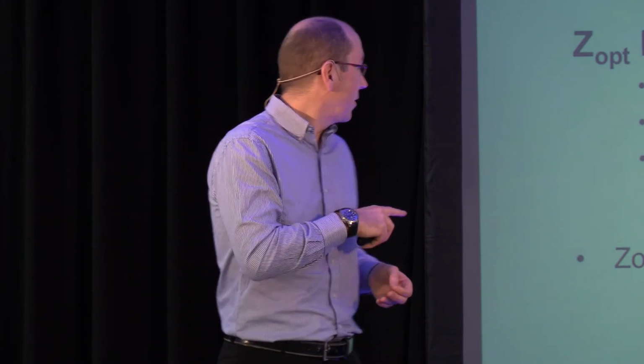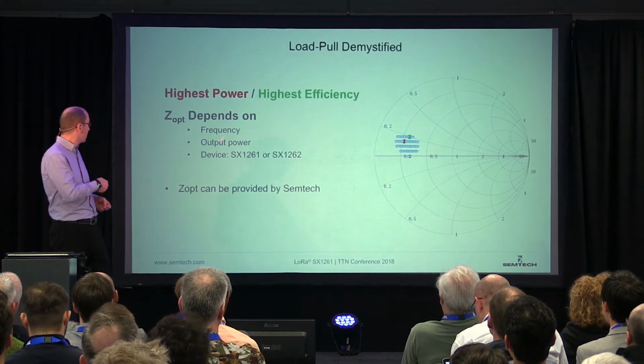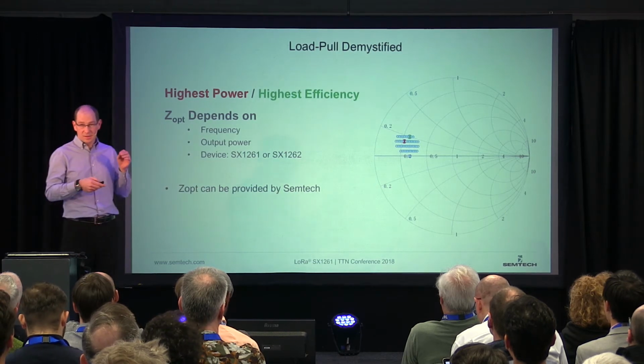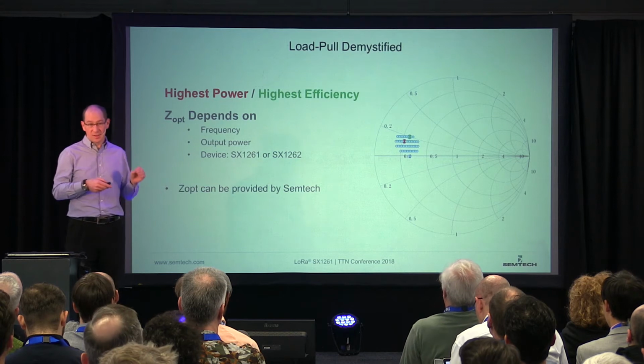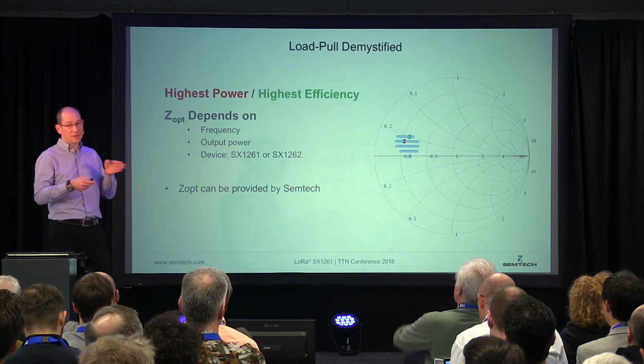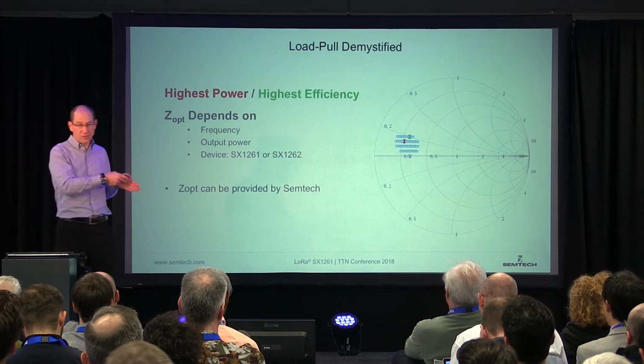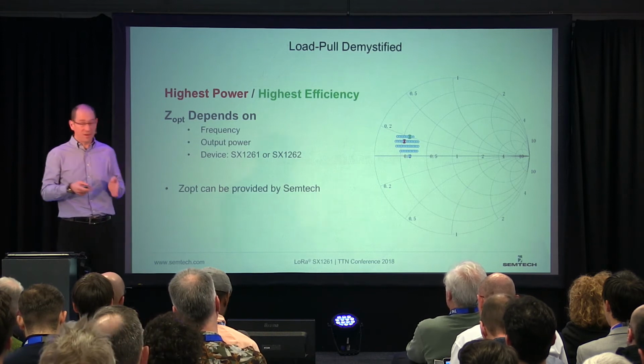But one thing here is that your Z-opt depends on your application. So it depends on the frequency you operate at. You won't have the same Z-opt at 150 megahertz and 900 megahertz.